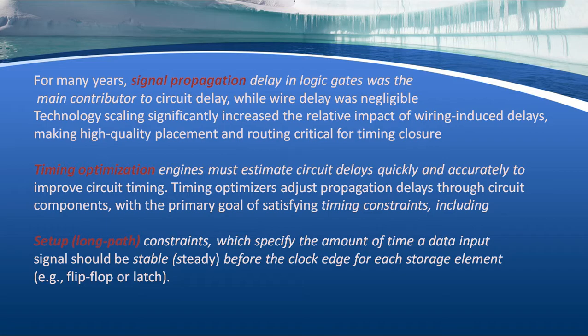That means data should be stable, should be present when the clock edge comes. If it is positive trigger, then for the positive edge, data should be present there and stable, and if negative edge trigger, then the data should be present for the negative edge.